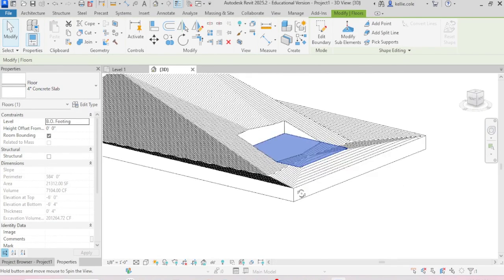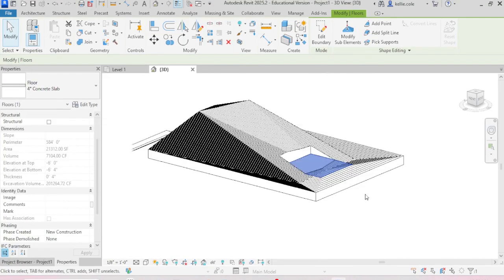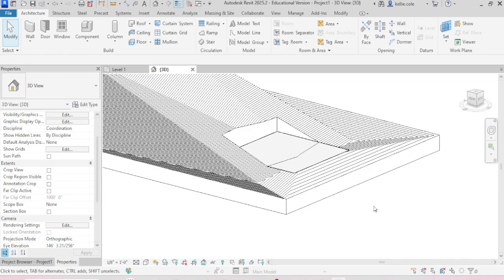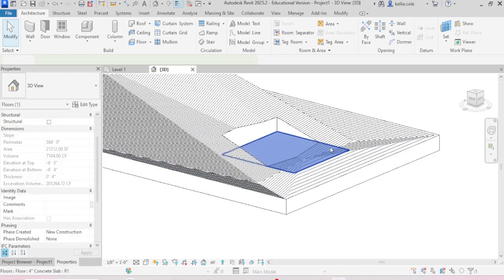We've been locating everything that we draft on the level 1 plan view at this point. We can change the elevation of floors in the elevation view. We've been working with the south elevation, or you can type in a numeric value using the properties bar.